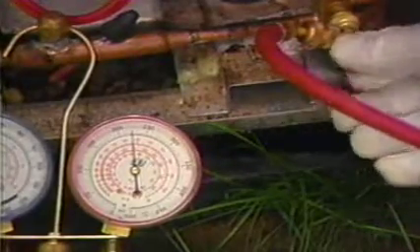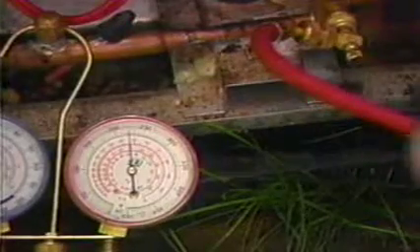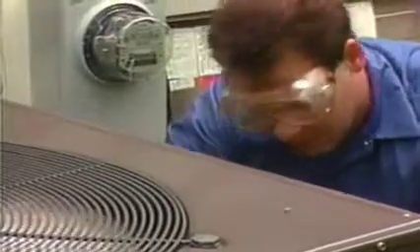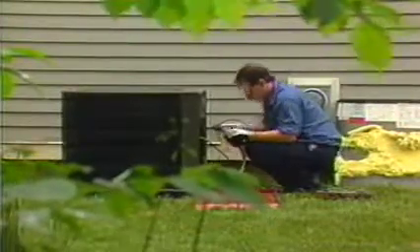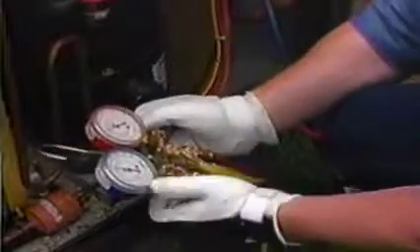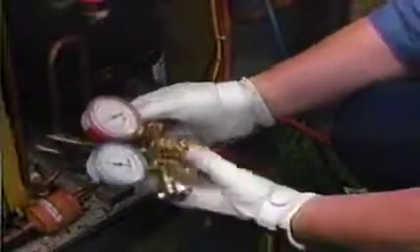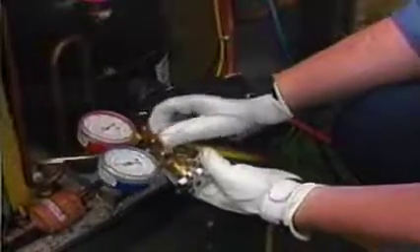This valve will be used to save the refrigerant in the high-pressure line when it is disconnected. Without this valve, the refrigerant in the high-pressure line would be lost when the hose is disconnected. The loss could be enough to alter the system charge. The technician then purges the gauge manifold through the center line.